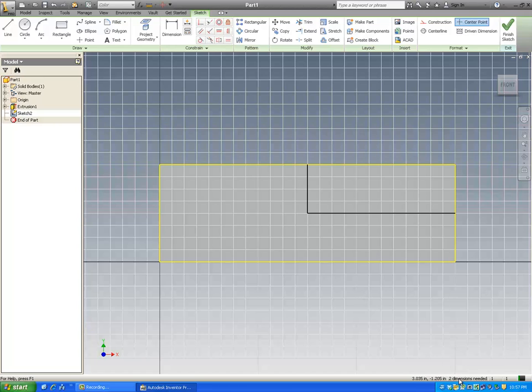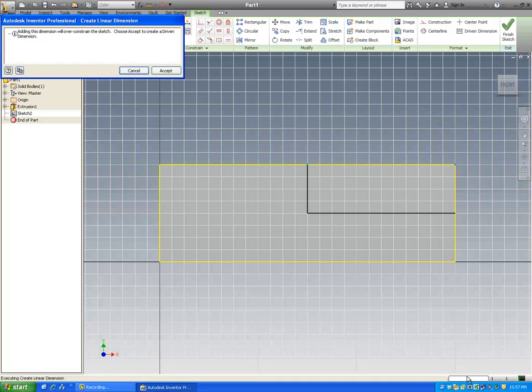If I look down in the status bar here again, I see I need 2 dimensions. So this is not fully constrained. So if I go up now to the model tab and try to work in the 3D environment and make this a more elaborate 3D model, I could be all messed up, because again down here it's not fully constrained. So I'd have to say, okay, well, I need this dimension. I need to know what that is right there. So that's 1.5.